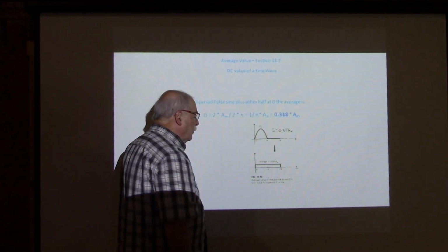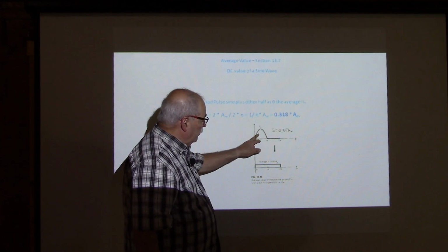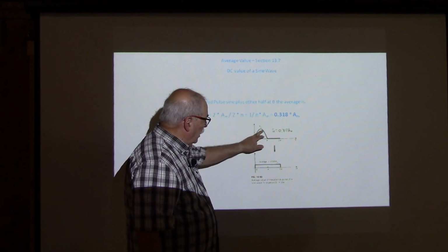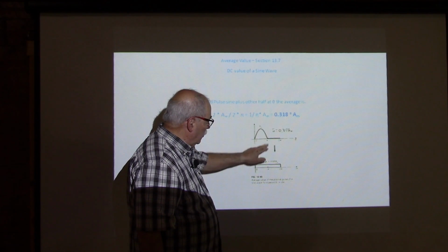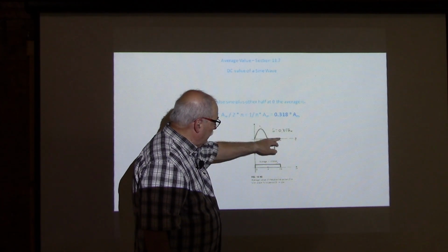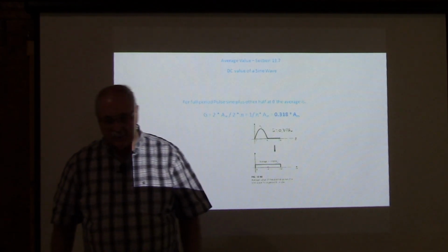And the reason you're remembering that is because if you're building power supplies or anything and you want to get the most out of it, you have to capture that negative half and flip it upside down. Right? It's a steering circuit, the bridge rectifier.